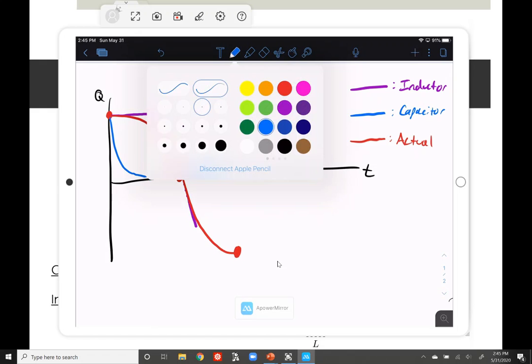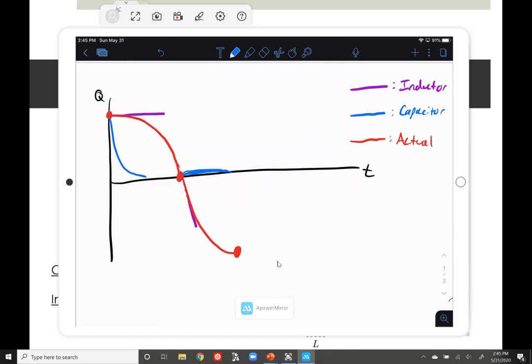And we ask again, what wants to happen? The capacitor says, well, we overshot. I would like to get back down to discharged. But the inductor says, we just got here and we just stopped the current. You can't reverse it immediately. I would like to stay exactly where we are. And you can see the sort of trade-off of what's building up here. We're building up to an oscillation.